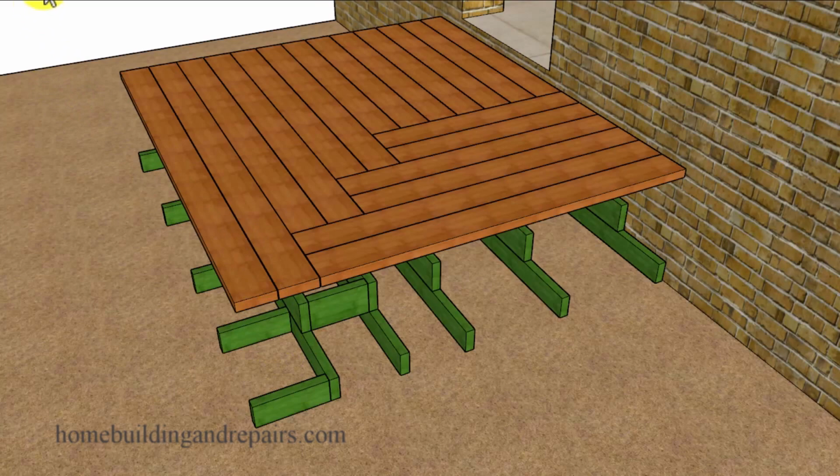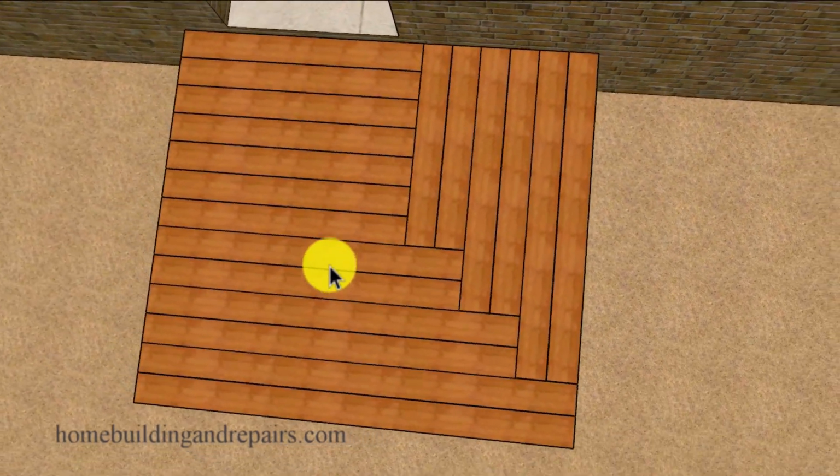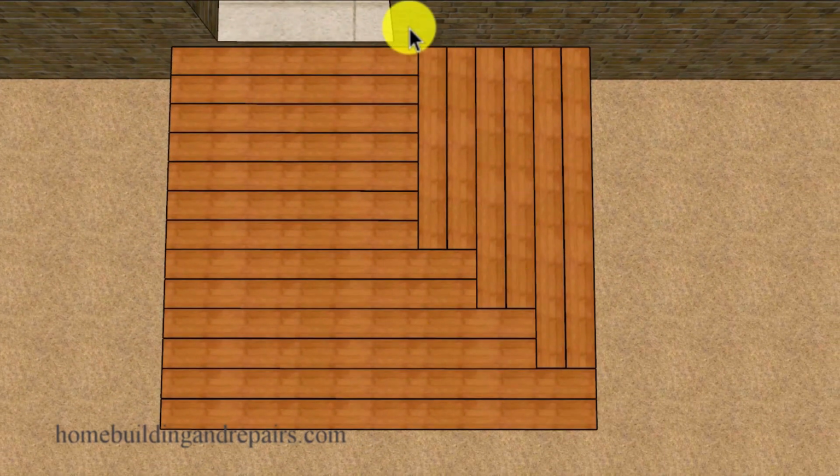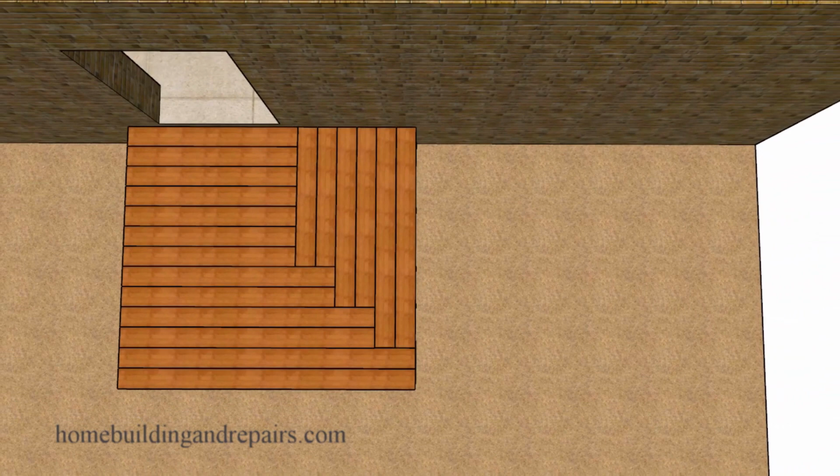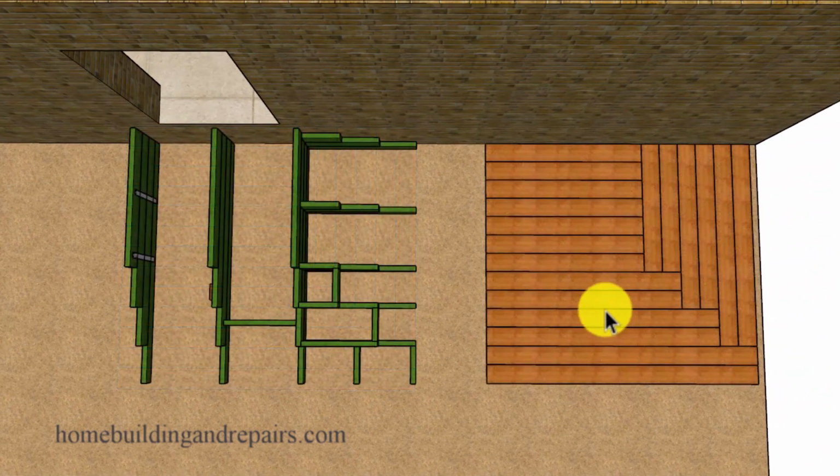If you notice, I've created a flat section here. And we're going to use each section here to calculate the lengths of our decking and stringer boards. And this is the beauty of this right here. This really makes your job easy. And make sure that you figure out the width and the depth of the deck before you get started. So in other words, you might not need to cut any of these boards.